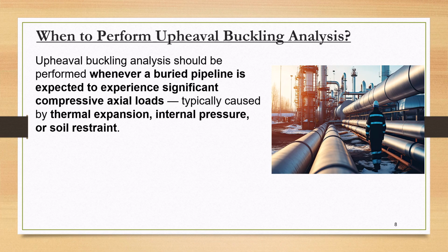Finally, during integrity management and fitness for service reviews. So in all those stages, you can perform upheaval buckling analysis, whenever a buried pipeline is expected to experience significant compressive axial loads, typically caused by thermal expansion, internal pressure, or soil restraint.